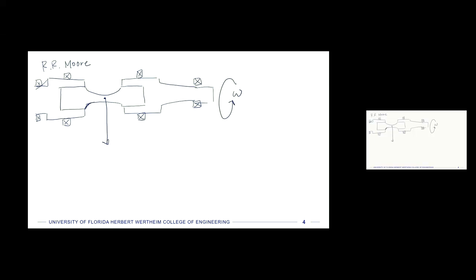The rotation, with a side load on the specimen, causes a fully reversing constant amplitude experiment on every location around the circumference.